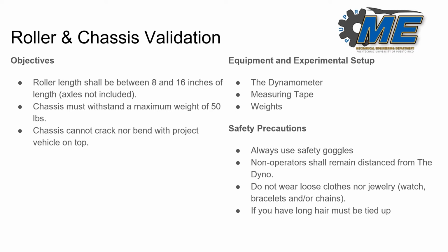For the safety precautions, we should always use safety goggles. Non-operators shall remain distant from the dyno, should not wear loose clothes nor jewelry, including watch, bracelets, and/or chains. And if you have long hair, this must be tied up.